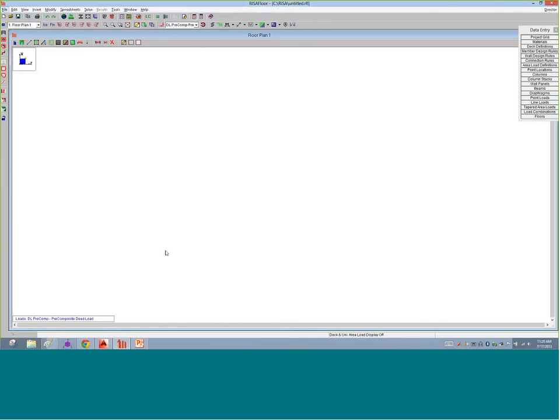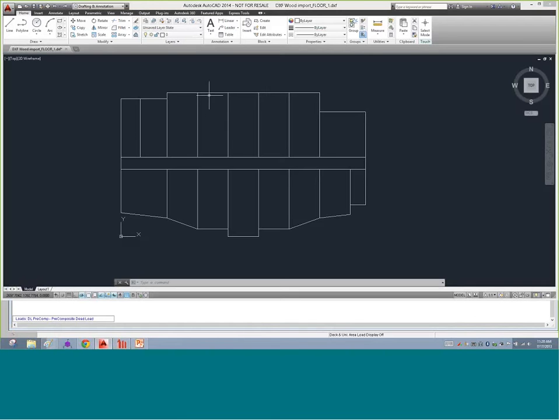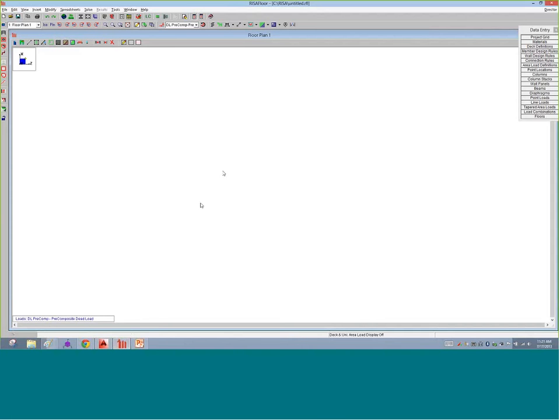If you imported it floor by floor, you could have drawn your model in maybe Autodesk AutoCAD, drawn it out specifically, and then brought it in. But if you have a large-scale model with a lot going on, I just drew a simple AutoCAD model here, and I just laid out what I wanted in AutoCAD. It was really easy to draw in AutoCAD, and I want to just bring that in and be able to trace on top of this. Now this is really great also if you have architectural plans and you want to just draw the structural underneath on top of it, you can do that as well.